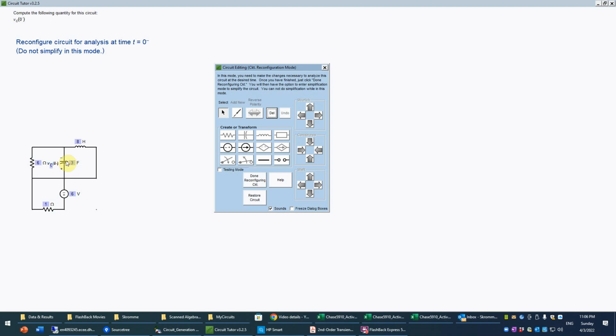And the next thing is, for the capacitor and the inductor, in second order problems, it's always necessary to find both the inductor current and the capacitor voltage at 0 minus. That isn't necessary for both of those in first order problems, but it is in second order problems, because these are the only 2 variables that will be preserved after the switch has acted. So since there isn't already a sought current on the inductor, we're going to have to add one there. This is an essential step.